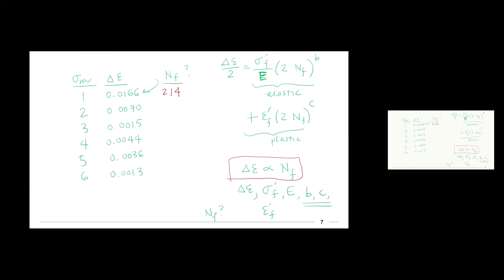But it's not just 1 or 2, because even though the maximum tensile goes up to our maximum allowable stress that we even defined, the cycle does not go back to a fully reversing minus 140, right? So our change in strain was not at a maximum. So we can get more than 1 or 2 cycles out of that. We get a couple hundred.